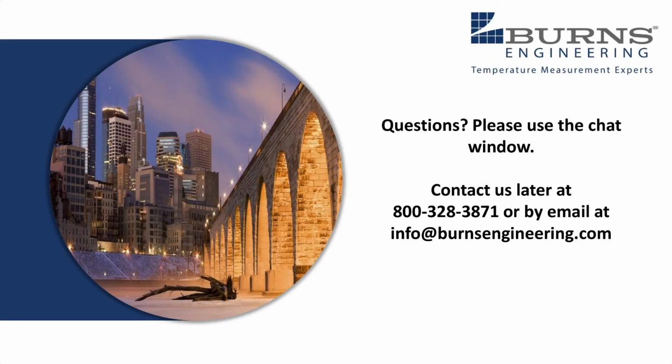So at best, the time constant from manufacturers just gives you a comparison point between different sensors. Well, this one reacts a little faster than this one. It doesn't actually tell you how long it's going to take to respond in your process. So that's something that's very specific to the process it's going into.